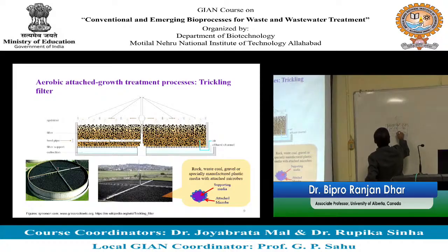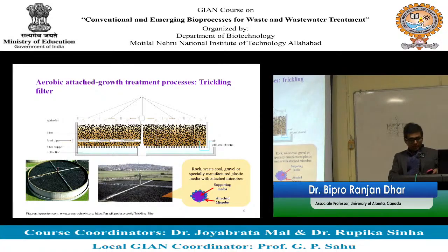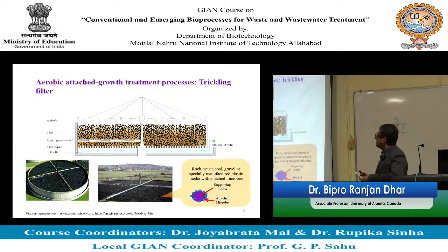Wastewater is going to trickle through the media bed. So you have microbes here, and when the wastewater flows from top to bottom, the microbes interact with the organics and treat the wastewater.